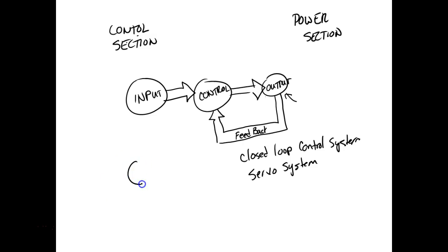I can have a relay that runs off of 24 volts DC, but the contacts it controls might be controlling 2000 volts AC. What's nice about a relay is that you can change the type of voltage that you use. So your coil might be rated as DC, but your contacts might control an AC system.